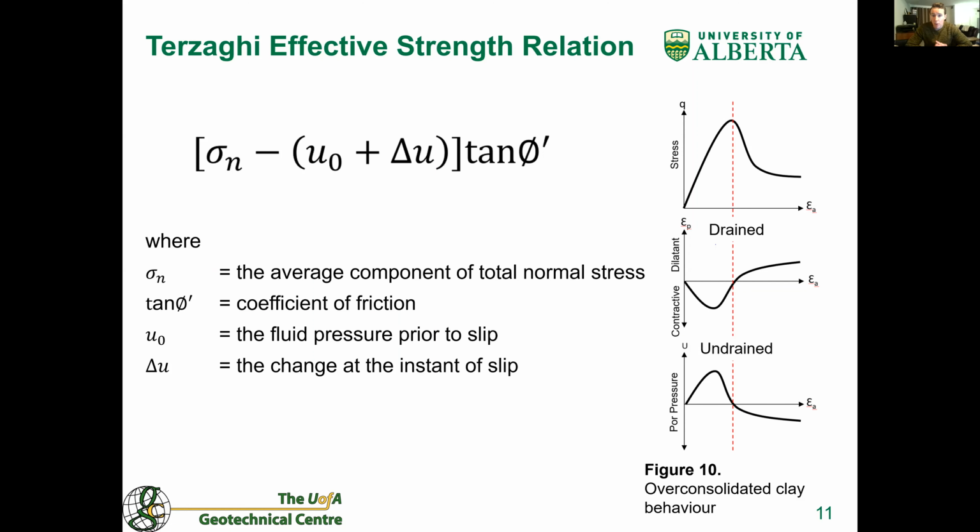This states that variations in pore pressures can be caused by volume changes, so dilatancy versus contraction, and that the volume change of shear planes, like those that develop during landslides, or of bedding planes, like those seen at Mont Terri in the Opalinus clay, are further associated with the stiffness of the stress-strain response of that specific layer or zone.